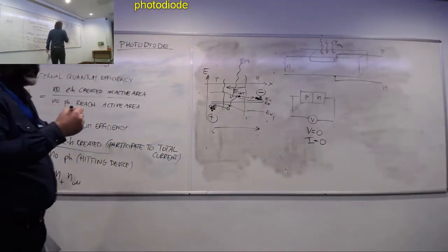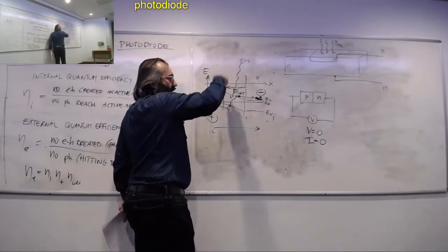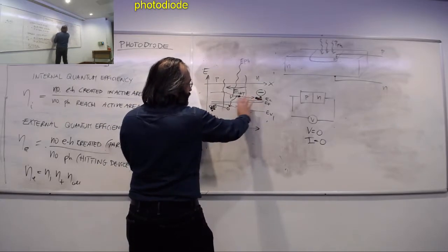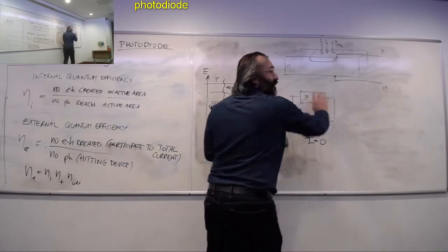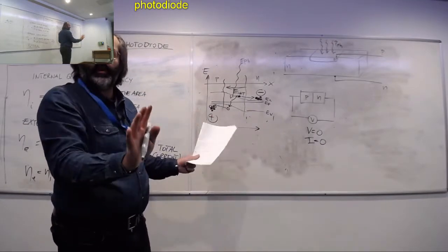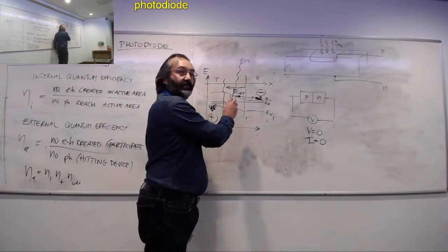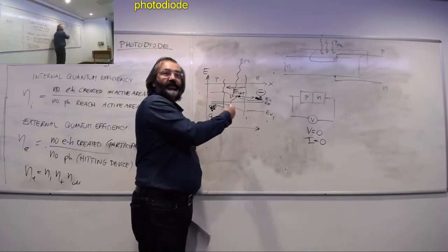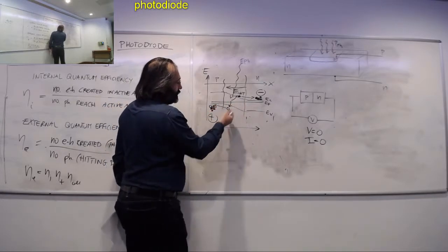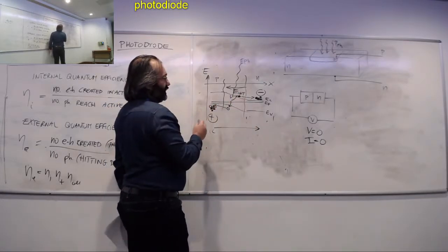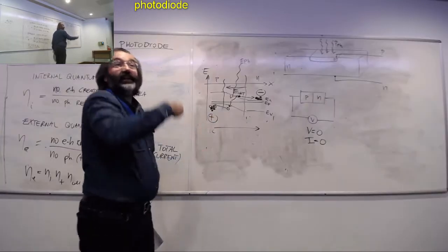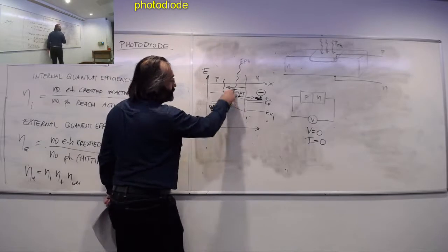So this means that while I shine light, the fact that these charges are, remember, the PN junction is not connected to anything. It's sitting there on its own, not connected to a circuit. I'm just shining light. I'm trying to understand what I'm doing here, what I'm causing. So we understand that there is an internal electric field, but the charge being separated also creates another electric field that is actually opposite to that.